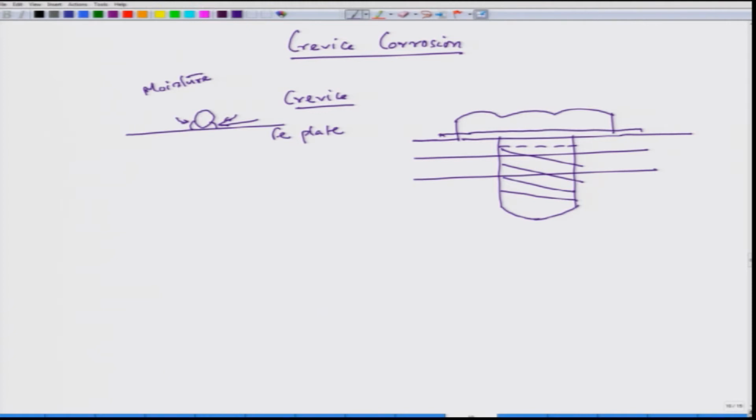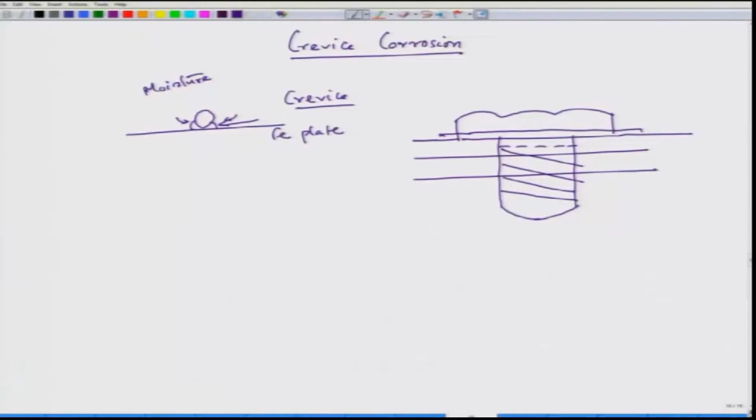What is the reason for this gasket? It tightens the joint and does not allow the bolt to become loose. But interestingly, if this gasket is a little wide, then the gasket end could have this kind of appearance, and it also forms a crevice. In that section, water can seep in and remain stagnant. This is another crevice region.